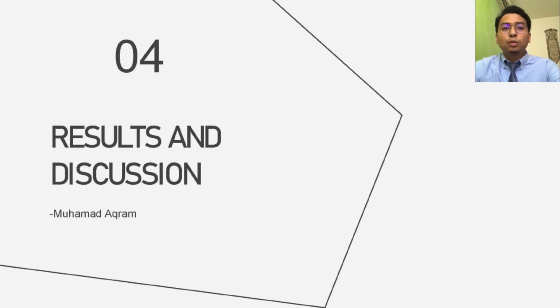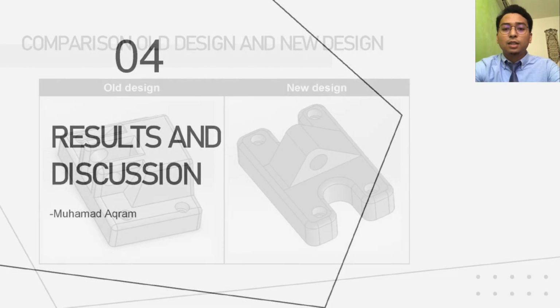This chapter shows the comparison between the old and new designs for the jet engine bracket. The old design used the conventional method to fabricate the part, but the new design uses an additive manufacturing system. After going through the simulation analysis for topology optimization, there are two main comparisons in this project, which include the complex shape of the new design compared with the old design. By using SolidWorks analysis, this project can optimize the shape using the same material, which is titanium. This project can also observe the percentage of part reduction or increase, part improvement and mechanical justification analysis.